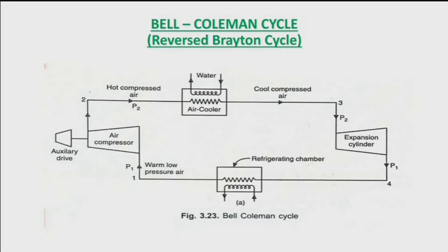So it becomes high compressed air, and the pressure becomes P2. Okay, from P2 that high compressed air passes through an air cooler. And as you know, when the pressure increases, the temperature also increases. So the high temperature compressed air passes through the air cooler, and you can see that the air cooler is cooling down that air by using an alternate solution side.